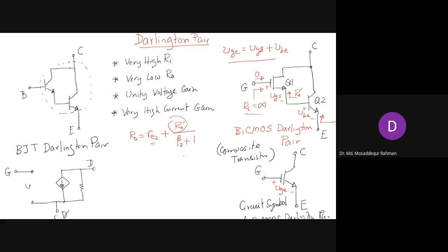Okay, so that is our voltage VGS, this plus and minus. It is equivalent to VBE for bipolar transistor. So here the gate is open, right? Why is it open at the input side? Because the input current is zero. There is no current flowing. So it is infinite input resistance, gate is open here.